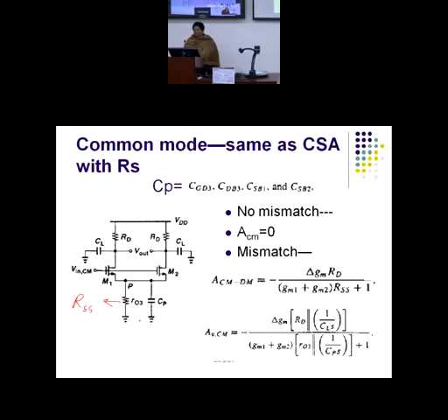So now what all I can do is that you can plot the frequency response for ADM and the frequency response for ACM. And then if I take the ratio ADM by ACM, what will I get? Frequency response of? Yes? CMRR. CMRR will not be constant. That value will keep on changing with frequency, because gains are changing with frequency. So the ratio will keep on changing.